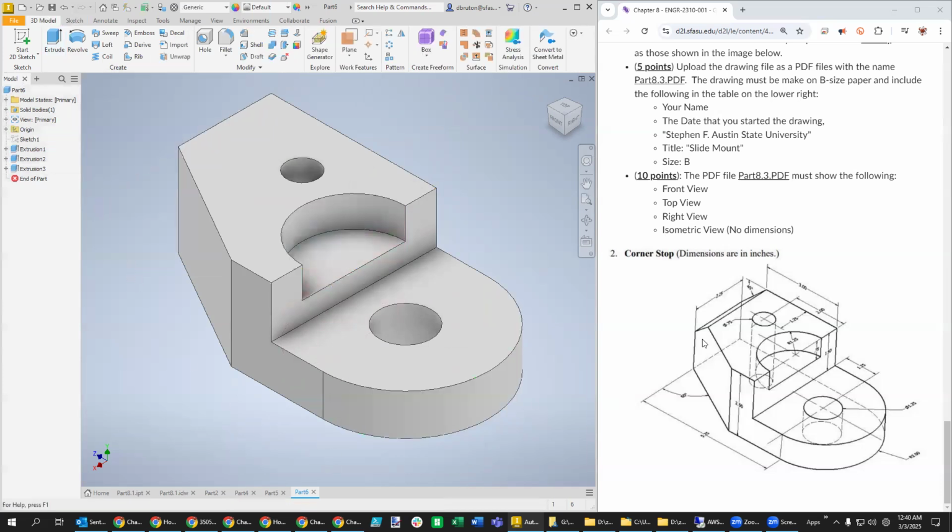Okay, there's one other thing we need to do, and that's to put a chamfer looking thing on the back side. The only thing is they don't really give us that distance, so we'll have to have it be implied that it's there. We can draw it on the back plane or on the middle plane, but we can't draw on this surface because it needs to be perpendicular to this back plane. So I'm going to try maybe just doing a sketch. You know what? How about just on the back side? So we can rotate the part around.